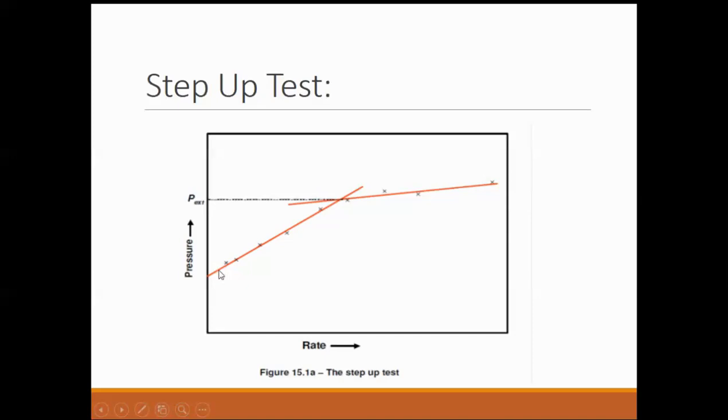So after the frac job, there is something called pressure matching. In the software, we collect the data during the frac job and feed everything into a simulator, and this is the sort of output it gives. Then you match the pressures, the pressure trend that you have gone through. So this is the blue line, the surface pressure which you got.